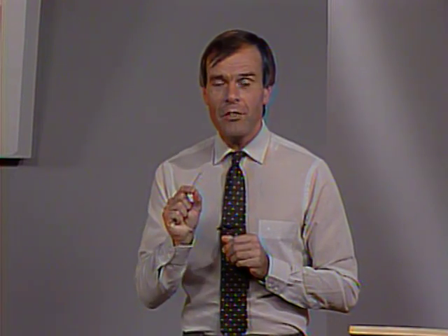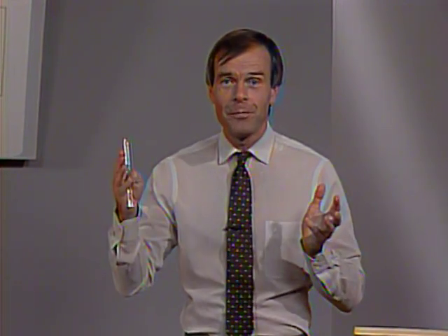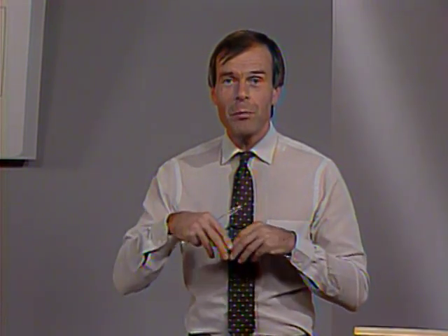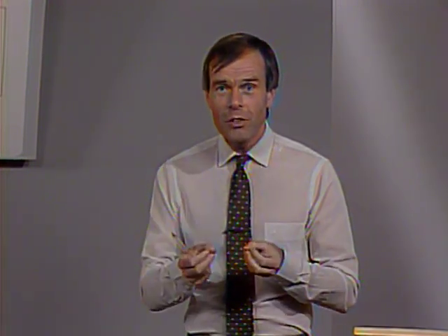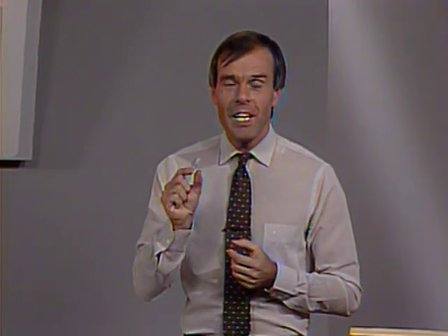If that is not the case, then you might have an instability for only a few time steps, and the solution may not have time to blow up or give you very large displacements, so the instability will not be obvious. Instead, the instability over these few time steps only introduces an error in the solution, an error of which you really don't know the magnitude, and after these few steps have been completed, you are using now a time step that is again stable, giving a stable solution.